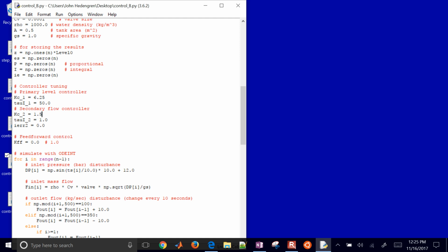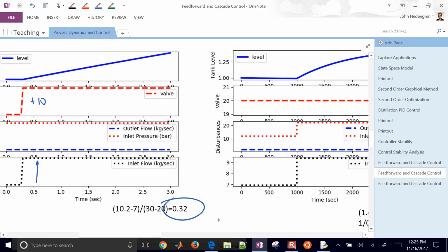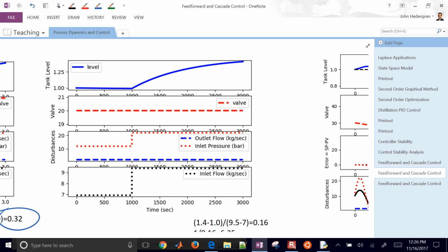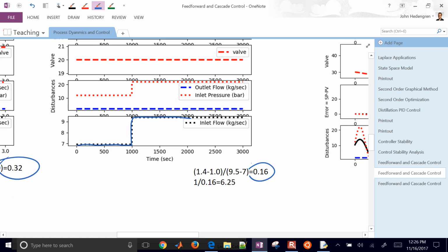So now with my secondary controller in control, I'm going to step the primary controller. So I'm going to give a set point change to the flow controller, and then watch how the level changes. Okay, so now I'm going to tune the outer one. So I've given a set point change to my inner one. It's going to follow that, and then you'll see the level right there. And I've computed a gain. And there's an initial guess for, this would be a good place to start my KC value. There's my KP. And so I'm going to use that one for my controller tuning.